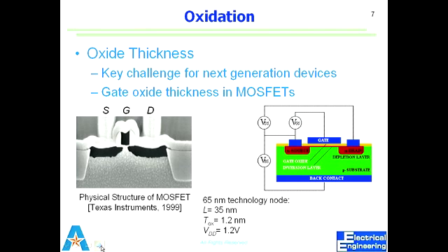And we still measure their thickness in terms of oxide thickness, in terms of equivalent oxide thickness. So we'll see what is meant by EOT, equivalent oxide thickness. The idea is that if you use high K dielectric, we can use a physically thicker layer of insulator and get the same capacitive effect that we get from oxide. Right?